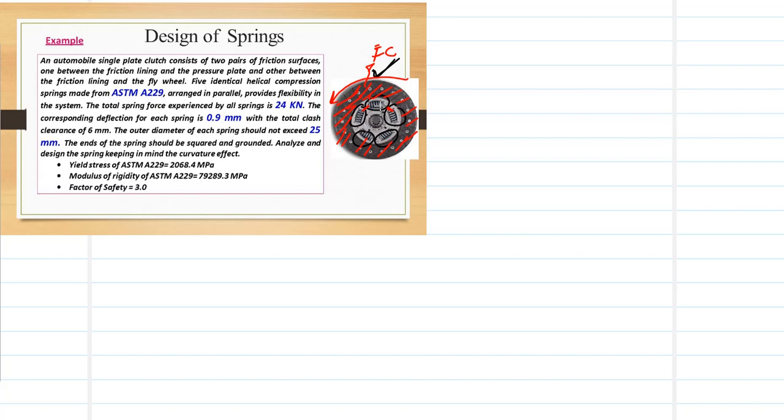So generally, for someone who has experience driving a car, this clutch plate will rarely wear out because of these springs. These springs actually provide a flexible contact which absorbs most of the shocks while changing a gear, to disengage between the engine and the gearbox.